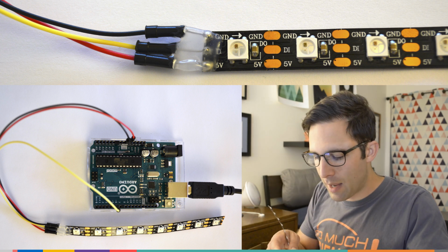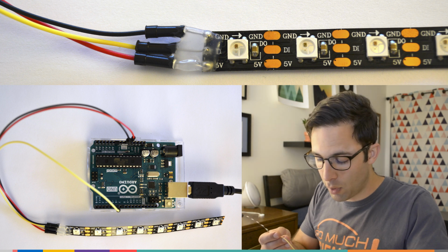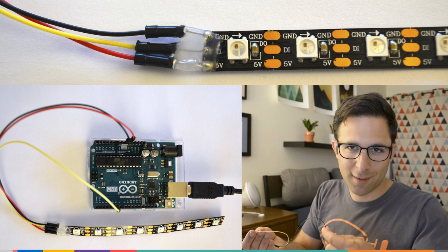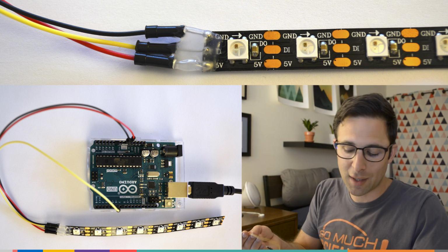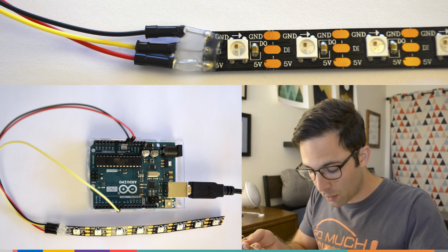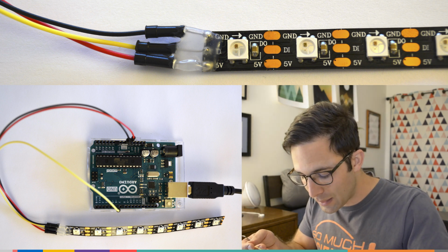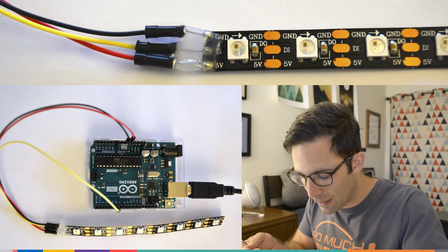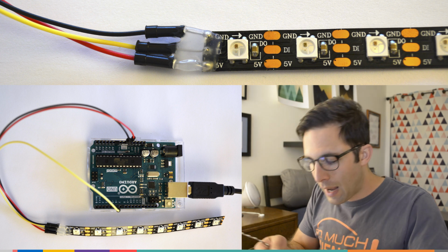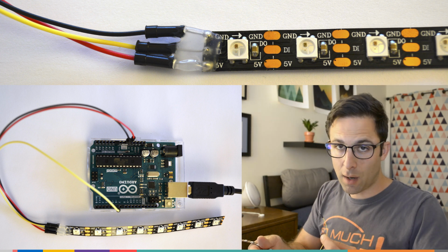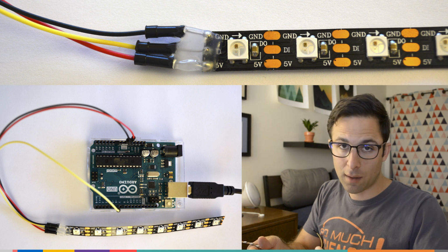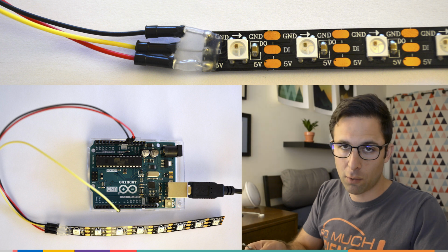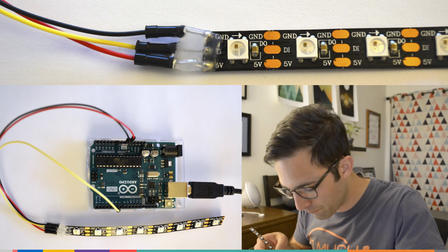All right, and then the black one, or whatever's connected to ground, because the color is really just the insulation we put on the wire. On the inside, it's all copper. It all conducts electricity. It doesn't matter. You put this on ground, and there are at least 3 different grounds, and they're all the same. So plug it into any pin labeled GND on the Arduino. And then, in this case, the yellow one that I have connected to the data, but it's whatever color you pick, connect that to the pin that you select in your code. And in our case, it's going to be pin 6.